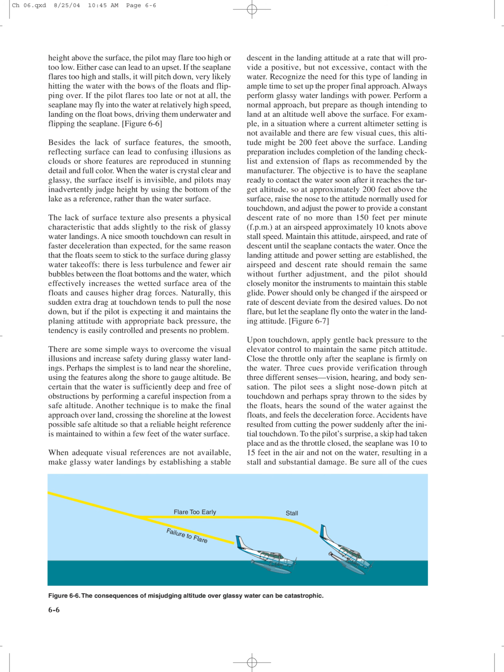Three cues provide verification through three different senses: vision, hearing, and body sensation. The pilot sees a slight nose-down pitch at touchdown and perhaps spray thrown to the sides by the floats, hears the sound of the water against the floats, and feels the deceleration force.